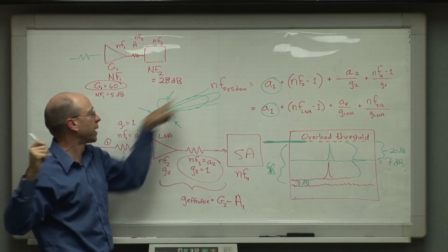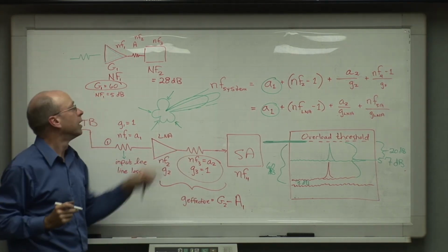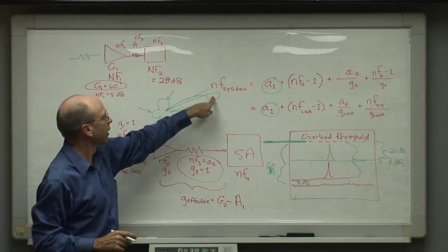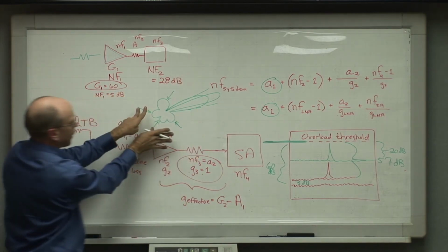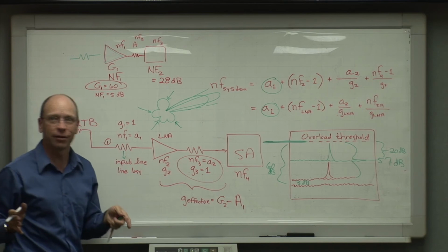I explained this on the phone. I said, it's not going to do any good. And they said, Frank, try it. And I said, okay, I'll try it. So I did, and sure enough, I didn't get any more, because what happens is you get more gain on the distributed energy that's inside the beam, but you lose all the energy that's outside the beam, and it turns out that the two factors exactly offset because gain is a geometric factor.